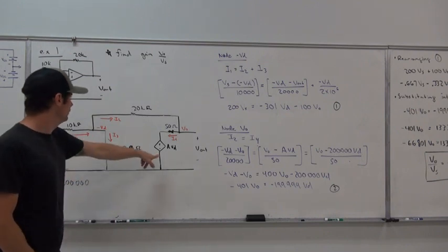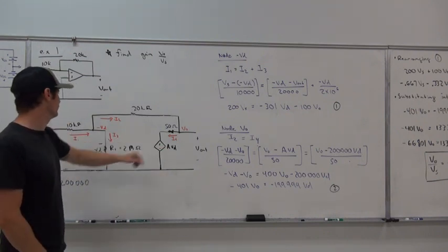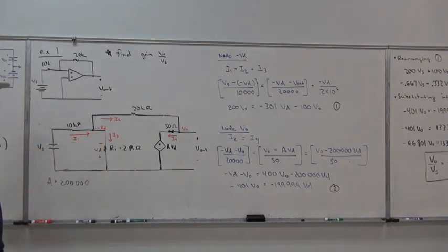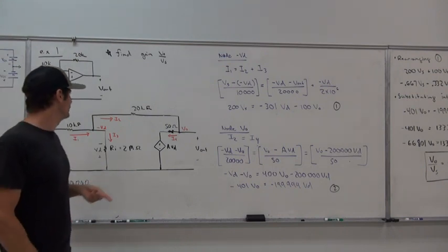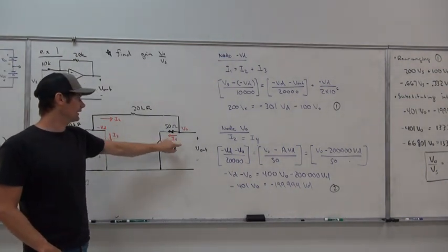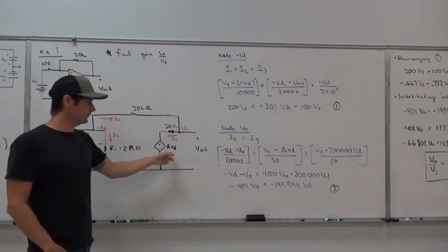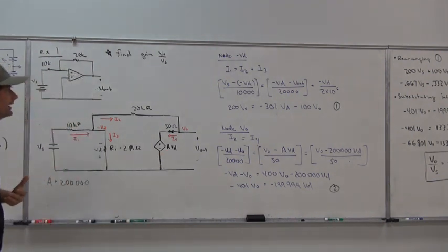And here, that dependent source, we're actually going to drive as basically being this value here. So I drew our currents, I1 going into negative VD, and outputs of I2 and I3. I3 goes through our internal resistance to ground, and then I2 goes to V naught, I4 leaves V naught, and goes to our dependent source with basically that open loop gain.